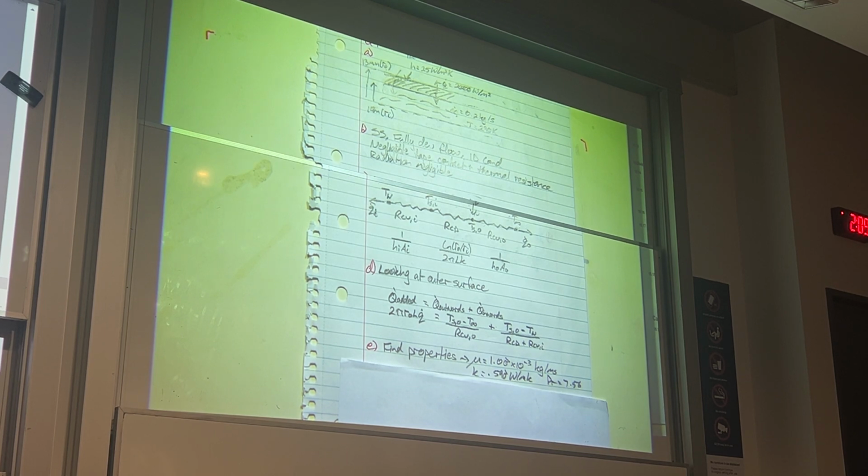Are we evaluating the properties at film temperature? Yeah, so it was given to us as 290 kelvins. So we should be sitting around 15, 17. So she probably has interpolated, because that's how she's got a different Prandtl number. She's just taken that thermal conductivity.